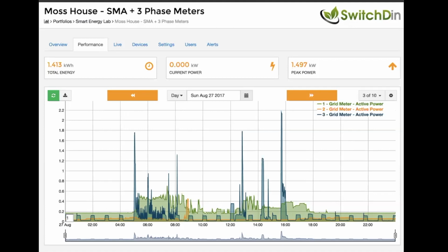Okay, and thanks, Glenn. Richard asks, do the maximum demand allowances from the off-grid standard that you described just then correlate to those in AS3000? Richard, I don't know if you were in at the beginning of the webinar, but I was just pointing out that it's actually quite different off-grid than on-grid, because on-grid you've got a huge capacity from the grid in terms of instantaneous surge. Even if your capacity control is a 60 amp circuit breaker, for instance, you can draw way more than that. But inverters often have much harder limits, and so your maximum demand is on real maximum demand, not maximum demand after diversity calculations that you would use in AS/NZS 3000.